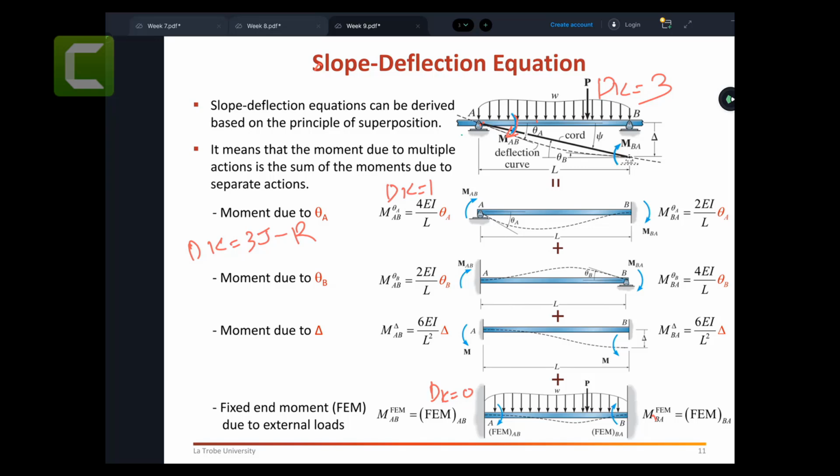So what have we done? Somehow someone goes there and removes 1 or 2 nails and removes that plate. Removing the plate allows that point A to rotate theta A. Immediately when you rotate theta A, you need moments to rotate it. Let's forget about theta A. Let's say someone wants to rotate that joint by 1 degree.